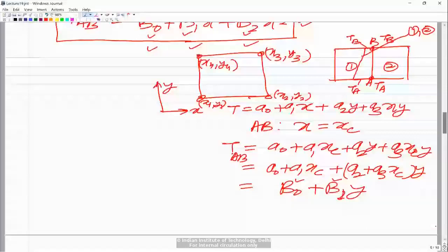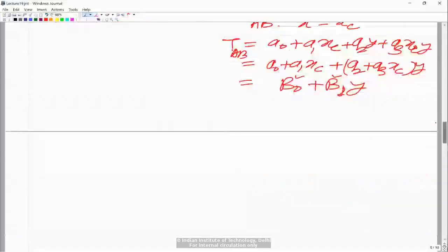So now, of course, we cannot always idealize and solve problems using rectangular elements, but we have to use arbitrary quadrilaterals. So for that, what we have is something known as the formulation in natural coordinate space. If we have formulation in natural coordinate space, then the element can be an arbitrary quadrilateral in physical coordinate space, but a square in the natural coordinate space. The interpolation is done in terms of natural coordinates, so it satisfies the inter-element compatibility condition. So next is the formulation in natural coordinate space.